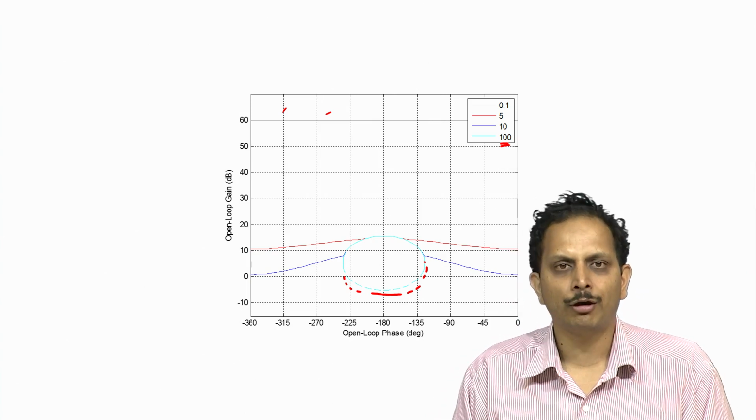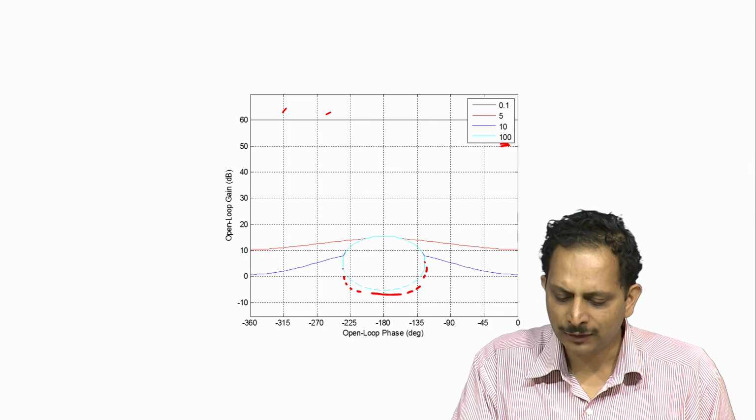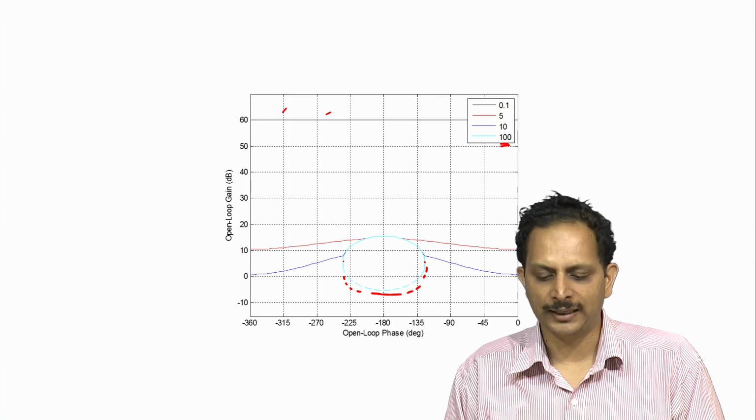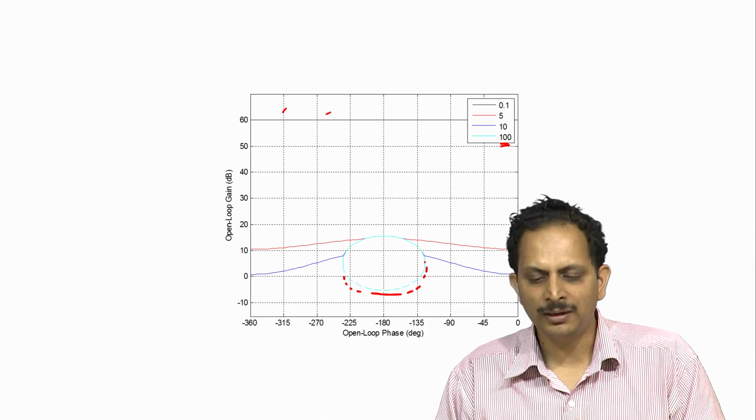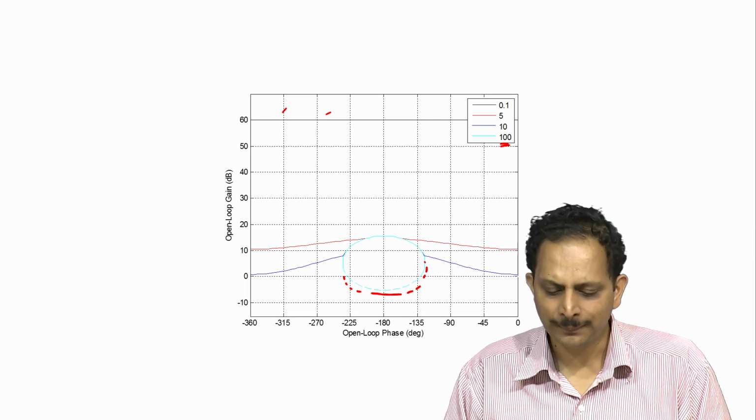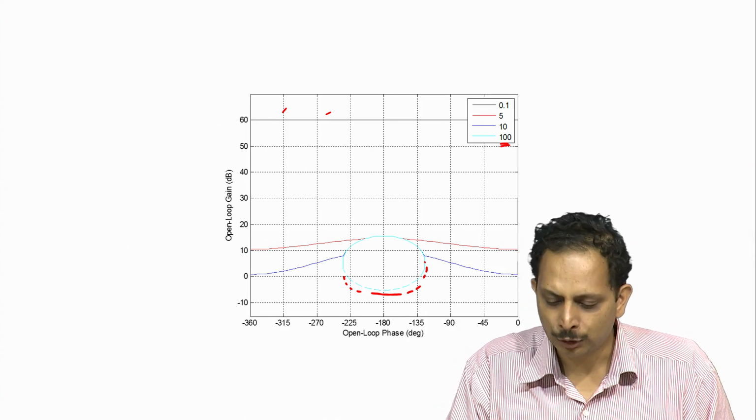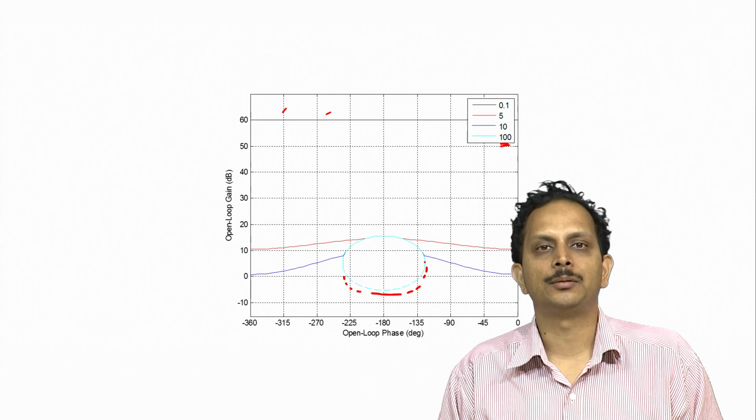And in this case we have picked 100 radian per second, and at this frequency we are concerned only about stability. So, for the system to be stable at this high frequency, whatever number it might be, it should lie outside this cyan colored bound.